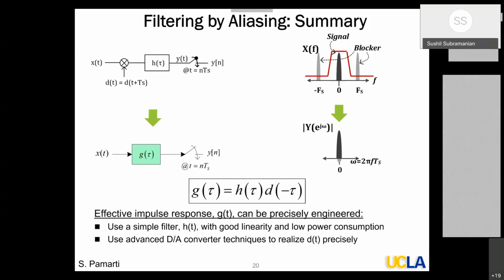So if I have a very large oversampling ratio, then the only option I would assume is to increase the number of time interleaving slices, basically. If you want a very large oversampling ratio, yes. Okay. So this has been designed for Nyquist sampling and nothing else. But like I was saying, if you typically do oversampling, then you want to be able to control the shape inside the Nyquist band. I think it may be possible, but we have not found a solution yet.